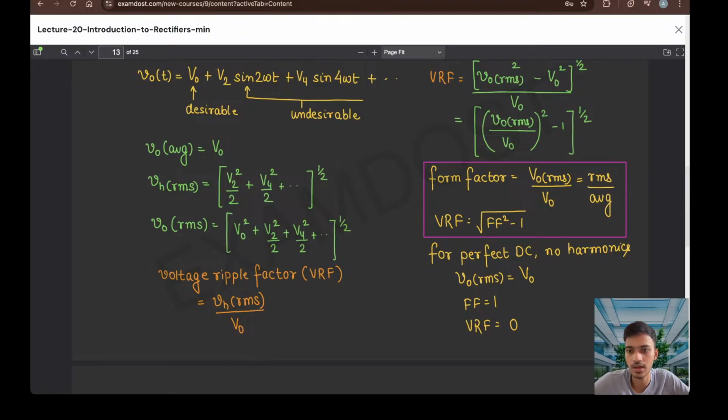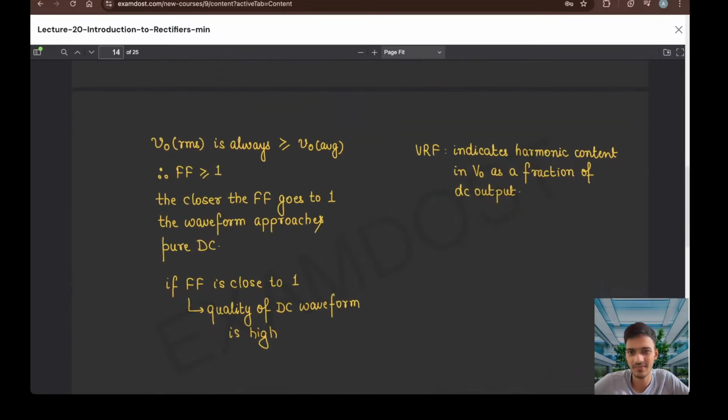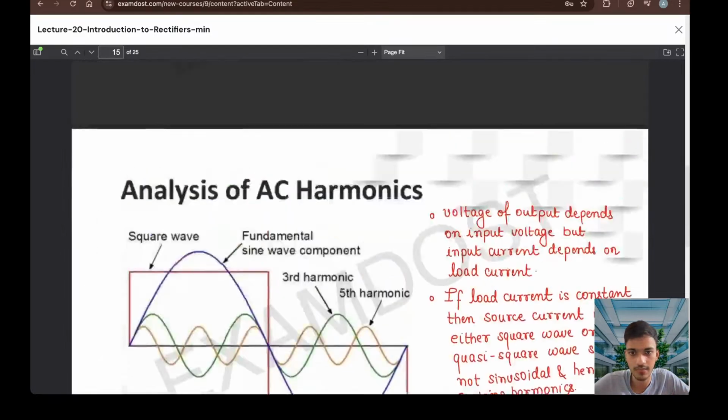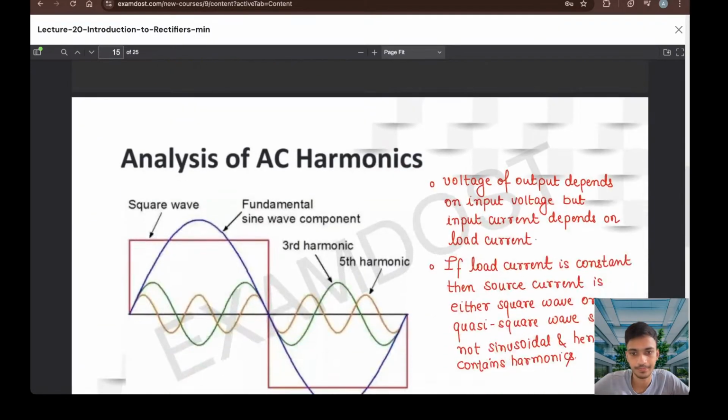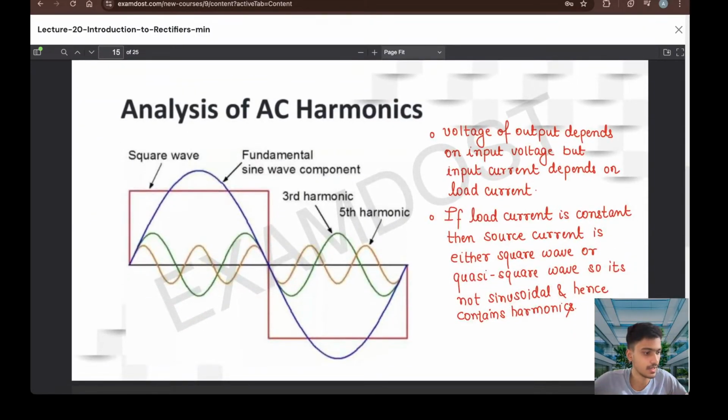एवरेज निकालो, आरएमएस निकालो, है ना, हार्मोनिक वाला. और इससे वोल्टेज रिपल फैक्टर में हार्मोनिक बटे एवरेज वाला आ जाएगा. उसके बाद इसको माइनस करना पड़ेगा, देन ही हमारे पास निकल जाएगा. प्रीटी सिंपल, उसमें ज़्यादा सोचने का कोई प्रॉब्लम नहीं है. VRF यही इंडिकेट करता है कि V0 में कितना हार्मोनिक कंटेंट है. VRF में V0 हार्मोनिक divided by V average, that is the desirable part.